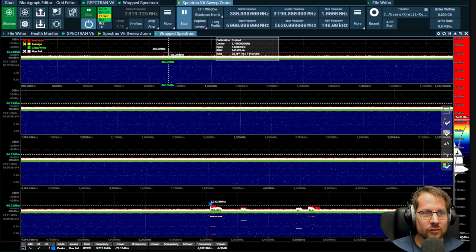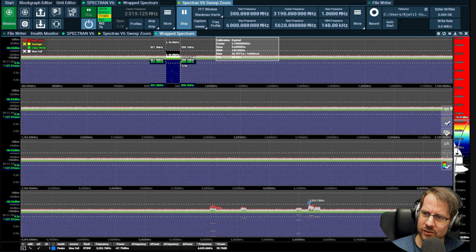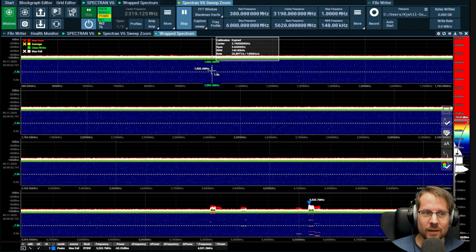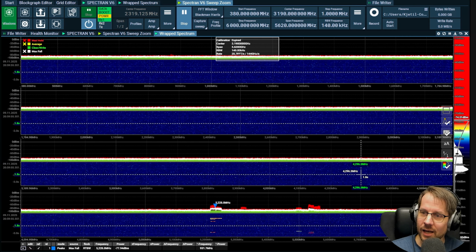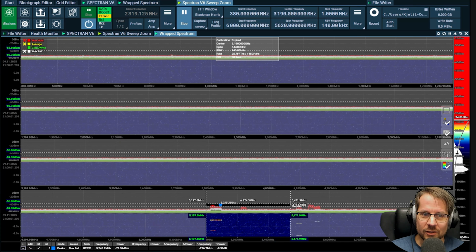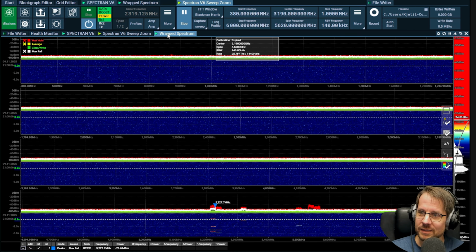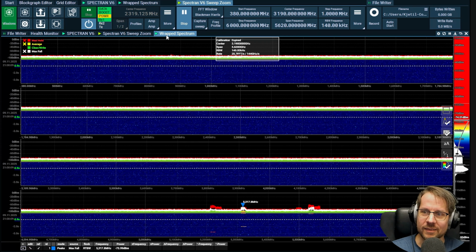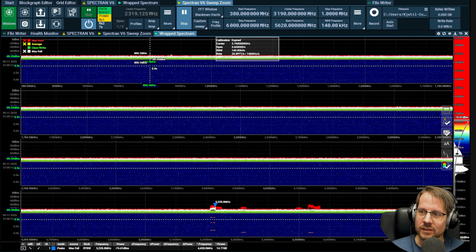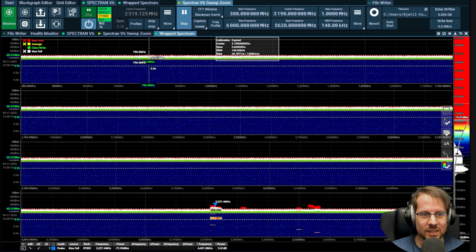You can see the small spikes up here, that is my power meter indoors. That is strong. If I have my antenna placed a little bit differently, it will trigger up to minus 10 dBm, minus 5, and it will create harmonics all over the place. But with a proper bandpass, high pass, low pass, you will get rid of all these kinds of signals. So now LTE is completely dead. You can't see it because the bandpass has attenuated all signals below 4.9 gigahertz with this particular bandpass.